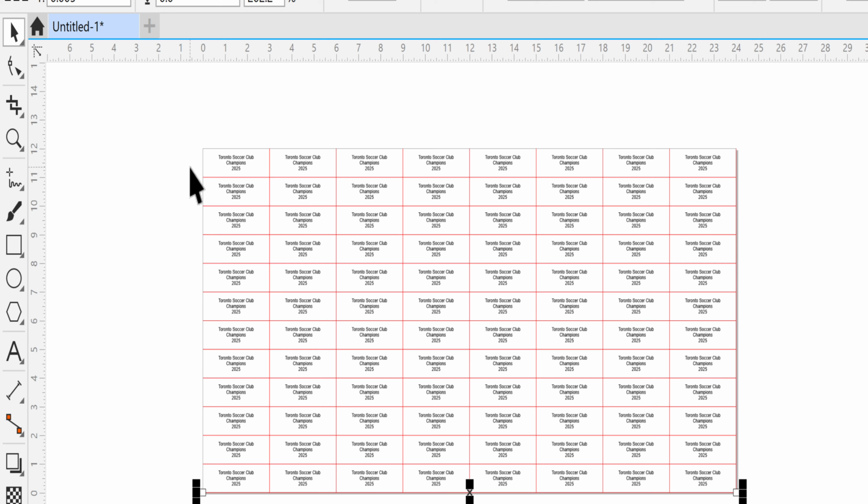So what we need to do is, we have a home node and we've got an end node. All the home nodes are basically right here, and all the end nodes are right here. I just need to change the end node and put a home node here, put an end node here, put in a home node there, and then back and forth. So the machine's going to be going in a kind of small Z pattern all the way down, and that will speed things up. Again, if you've got a small machine, it's not a big deal, but if you had a large machine and could speed the process up, then it's certainly a lot better.